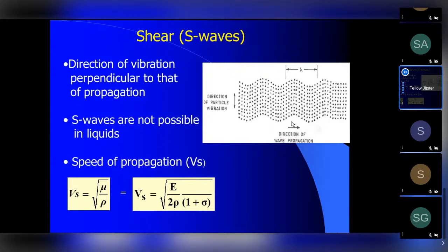If I have a line, like the direction of wave propagation, there can be two directions perpendicular to it, or only one. So two perpendiculars. Very good. So we have two perpendicular directions. One is the one that makes the up and down motion like this, that is called the horizontally polarized shear wave, and the other is called the vertically polarized shear wave, SH and SV.